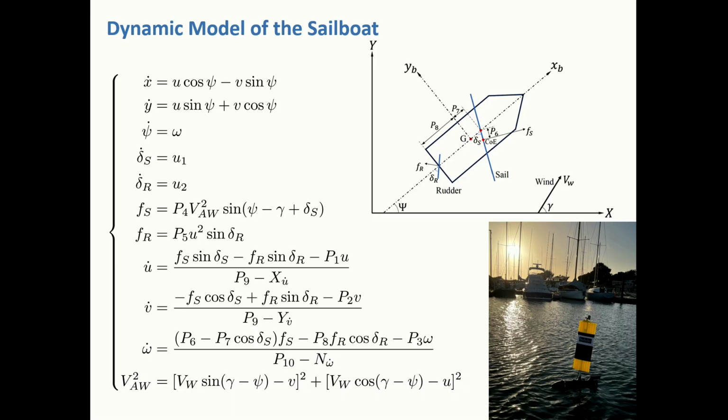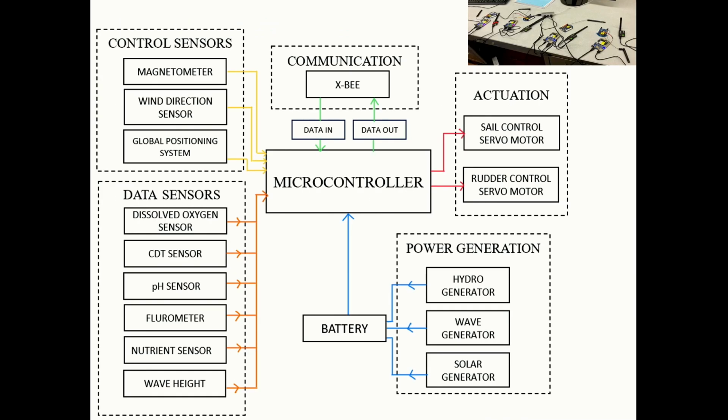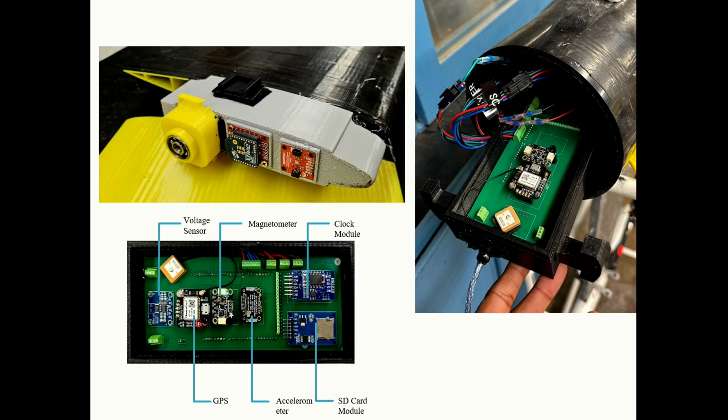All right, so this is a little optimization here and there, and the controls. I mean, sailboats are complicated. We have sail, we have rudder, we have the keel, also the coupled set of equations. A lot of electronics involved, the sensors that we have: magnetometer, IMU, the GPS sensor to know where it is. So GPS is really the critical one to measure the velocity of the current that we want to measure.